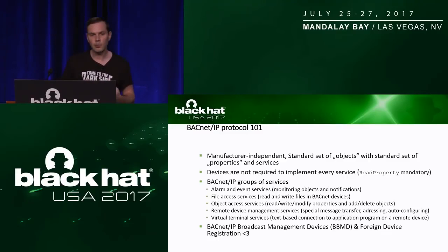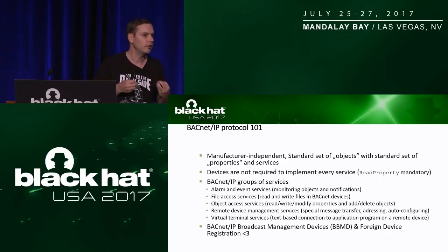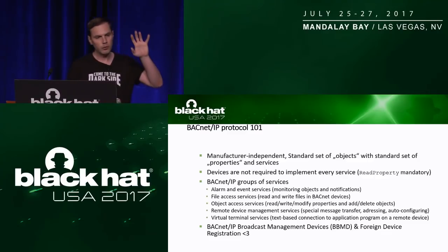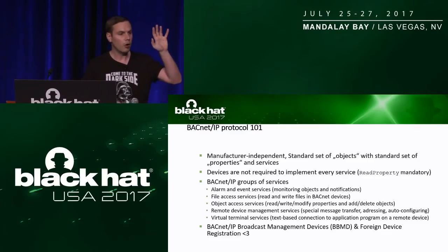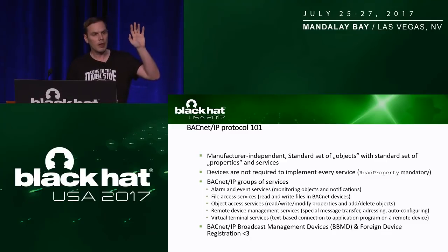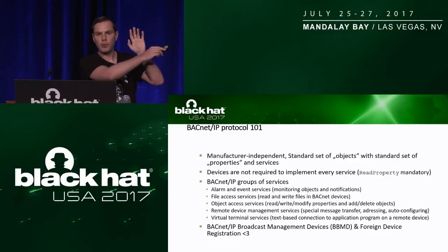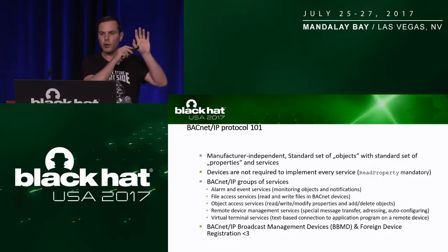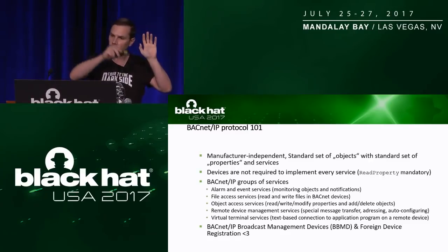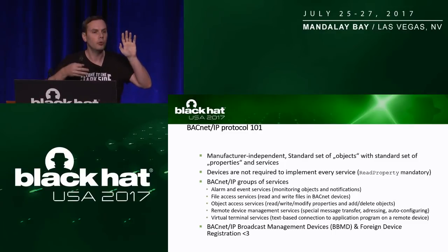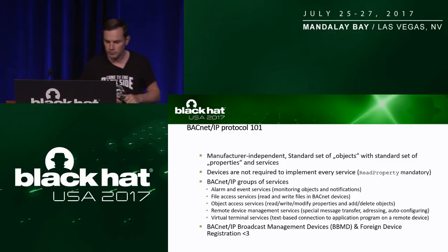Why do we find it interesting? Because it's a perfect function to compromise network security, even if you actually did network security right. If you think about, you have a BACnet IP controller on a private network, and for service purposes, somebody requested that the BACnet port is port forwarded to the internet. If this device provides this BBMD function, you can register from the public internet to the service, and from that point in time, you will be able to talk to all the internal building automation controllers as if you were in the same internal network.